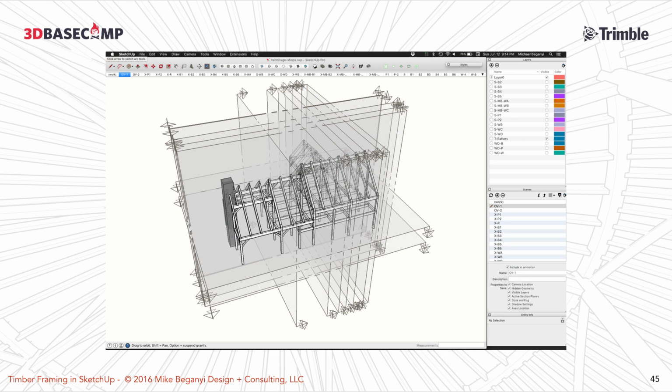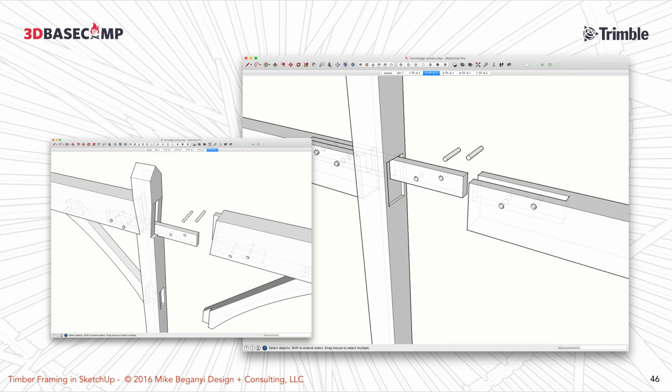But again, here's a typical set of shop drawings. This is a model of a house, a screenshot. So I've got my layers. I've burned out all the layers I don't need for my template. I've got a ton of scenes. All those scenes represent something that I need to show off in Layout. And then there's a couple scenes in there just for working. So each one of those section cuts will relate to my drawing. And then again, I have a separate model where I pull everything apart. And this one I actually do have loaded.